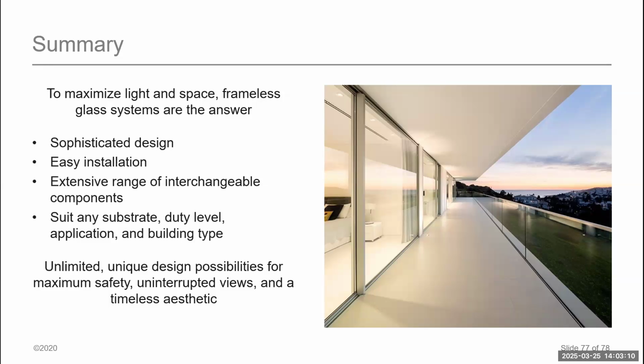The other thing that I do want to touch on just real quick that I didn't talk about in the glass is as glass gets wider, it actually does not get weaker in a glass railing system. The fallacy is when it gets smaller, what we do is we create a slenderness ratio in the glass, and the glass will have a tendency to want to break. So you need to look at a standard when you're dealing with 9/16 laminated of 36 inches minimum wide. And then as you move on to 11/16 and 27/32, you can start getting 30 and 28 inches. And when you move to 1 inch, you possibly can get to 2 feet. So thank you very much. Appreciate it. And at this time, I will turn it back over.